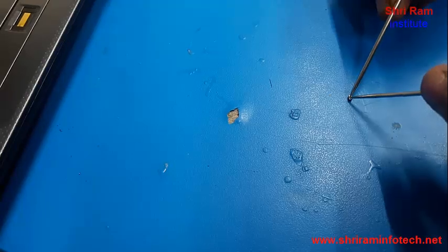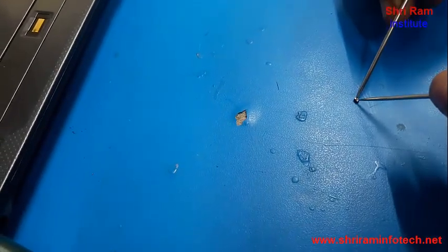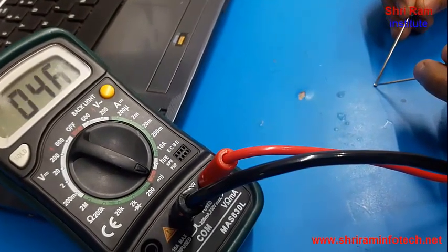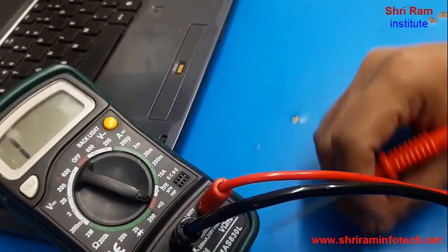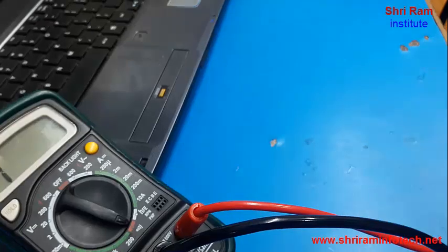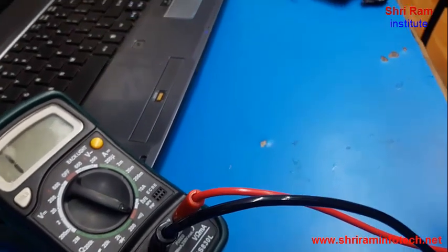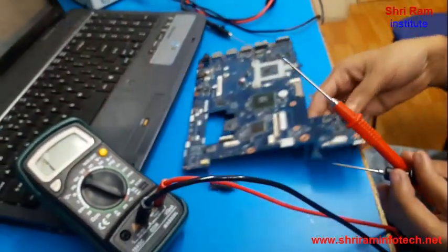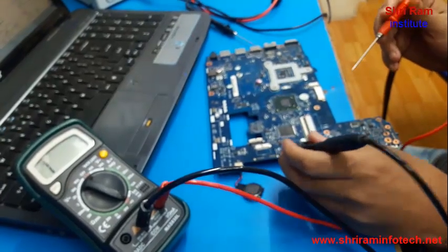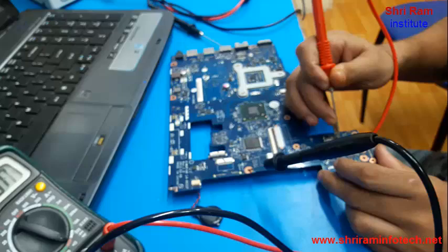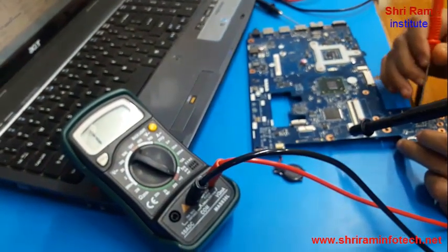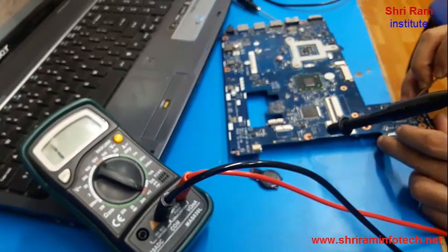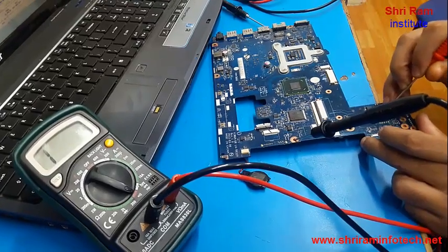Now we are going to check in buzzer. This capacitor also shows short. Now this capacitor is also bad. So we'll check the motherboard again. There are two capacitors that are short on this motherboard. One point connect to the ground, and another point at that current sensing resistor. See, now the short circuit is gone, the resistance has gone to infinite. That means the short circuit is gone, the problem is solved.